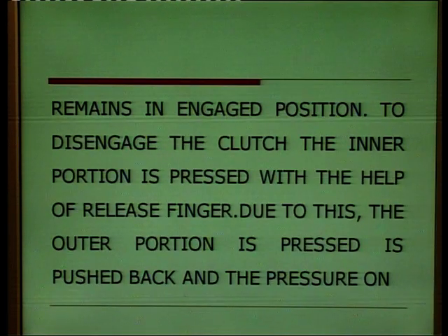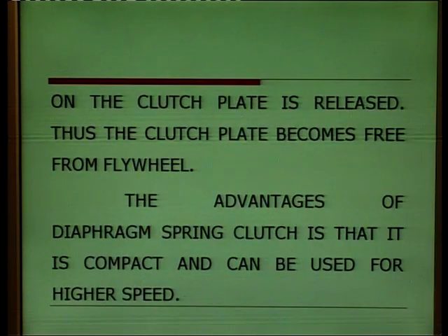with the help of release fingers. Due to this, the outer portion is pushed back and the pressure on the clutch plate is released. Thus, the clutch plate becomes free from the flywheel. The advantage of the diaphragm spring clutch is that it is compact and can be used for higher speeds.